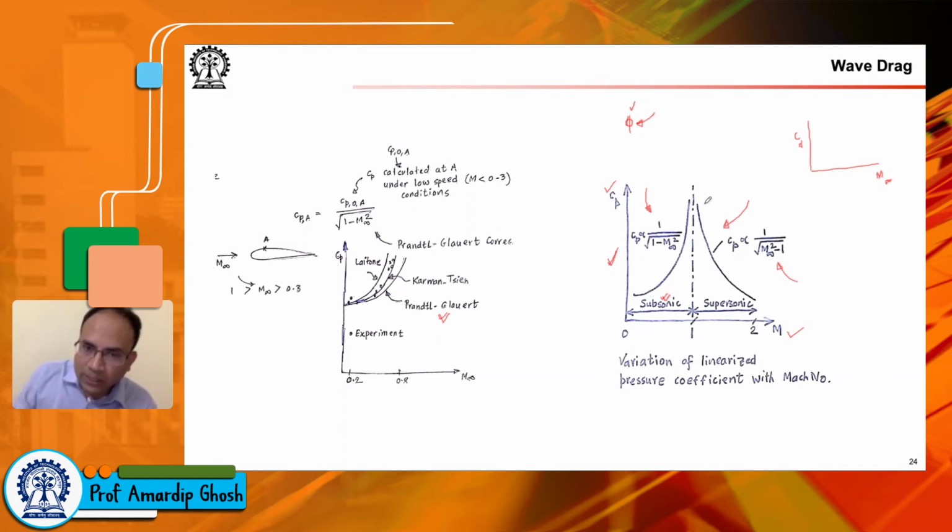And in terms of the wave drag, if you have flow separation, etc., it is really the imbalance of pressure. So it is influenced by the Cp distribution in the fore part and the aft part of the wing. So there also this 1 minus M square influence shows up in a similar fashion, creating that large rise in CD as we reach Mach 1.